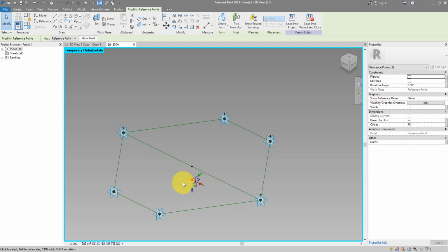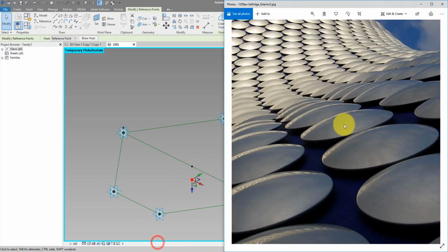The reason why we need this second point is, if you look at the reference image, the underlying surface, which is in blue there, is curved. If our panel's center point is right on top of this surface, when the curve gets extreme, our panel's edges may come clashing into the surface underneath, and that's not very nice. That's why we need to have this second point here to offset the panel up away from the underlying surface.